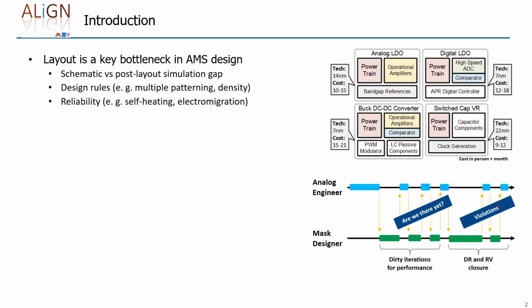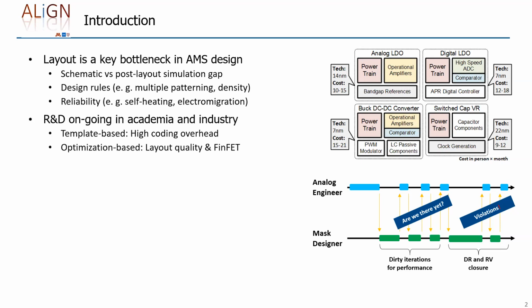The first objective is really to get post-layout parasitic feedback. So that's why these early iterations are quick and dirty. They are not DRC clean or not necessarily LVS clean. But once there is more confidence that the specs can be achieved, that's when design rule and LVS closure begins. Sometimes a significant violation is found last minute, which requires either significant layout effort or even revisiting the schematic sizing to accommodate the changes.